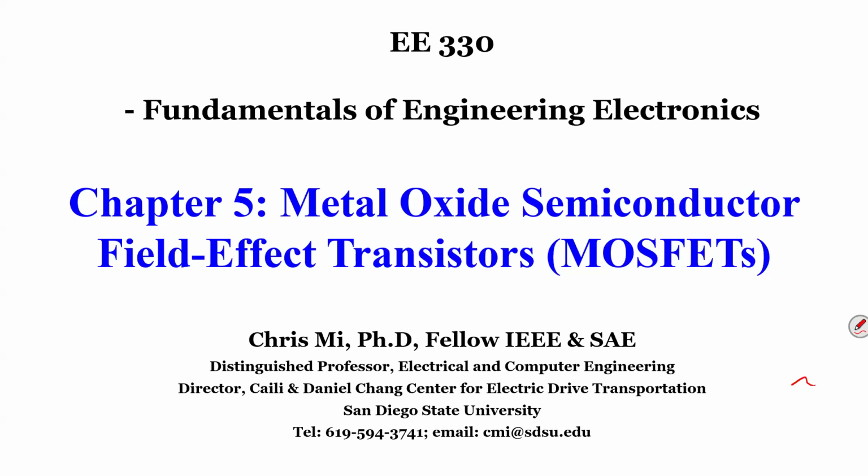There's no way to linearize MOSFETs and BJTs. We do that in the power electronics class, 584, where we say either on or off. But in this class, all focus is on the small signal: very little voltage, very little current, but they always operate in a region where it's nonlinear. So what are we going to do?